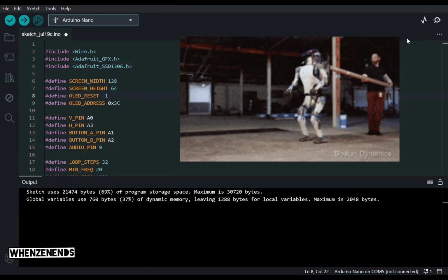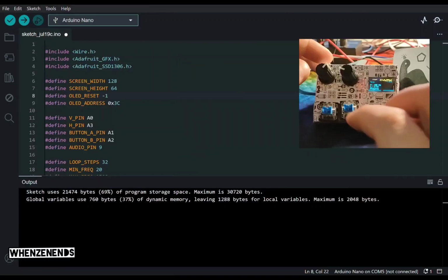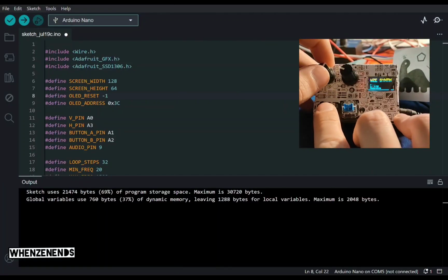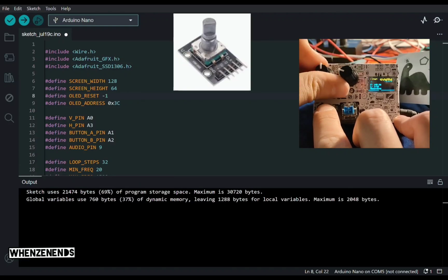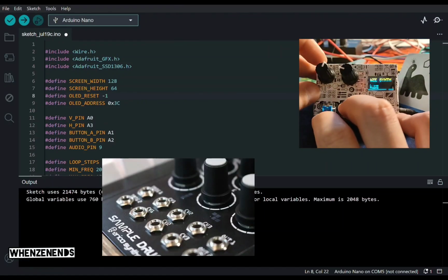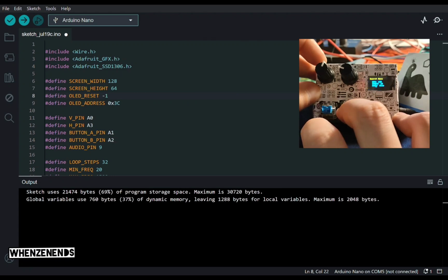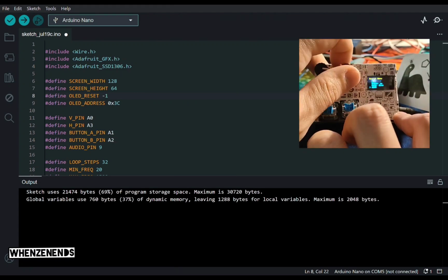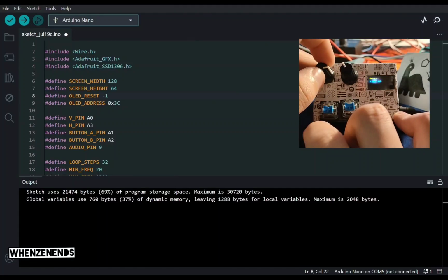This project isn't entirely complete yet. There are still a few things that could be improved. In the future, I aim to replace the potentiometers with rotary encoders to enhance selection accuracy and also add a CV input and output. I wanted to use the Mozzi library to create more interesting sounds, but I encountered a conflict with the library. Despite this, I decided to upload this video to help those interested in Arduino music projects get started with a functional and straightforward setup.